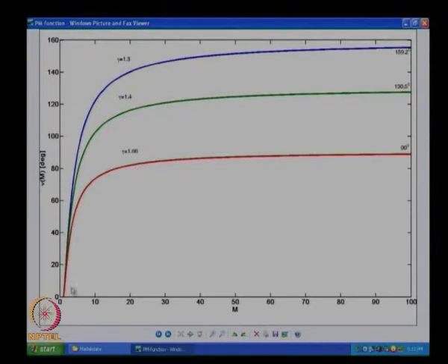If I am going from one Mach number to some other Mach number, the flow can turn a lot more, expand and fill the region more, if I go around a corner. We did that particular example for M tending to infinity last time, and we found that for gamma equal to 1.66 it just turned 90 degrees and stopped, while in the other cases it went farther. It is going to the same Mach number, but it is filling more space. It is more expandable, similar to looking at a more compressible gas. That's one way of looking at things.